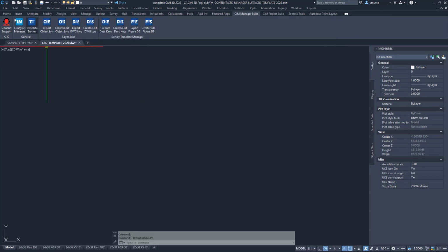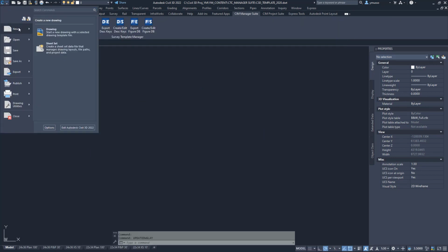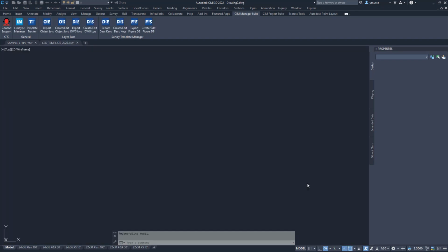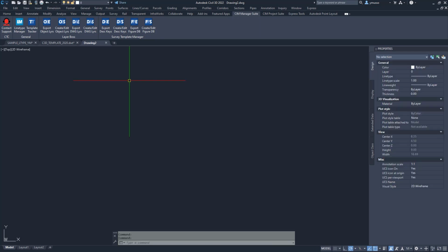When creating a new template, click on the Application menu or the big C. Select New. I will start with Open with No Template Imperial. You can choose any of the template files. The most favorable order of importing from a drawing, a template file, a template from out of the box, or an old template that has most of what you want in it, and or creating new objects is to do the basic AutoCAD objects first.